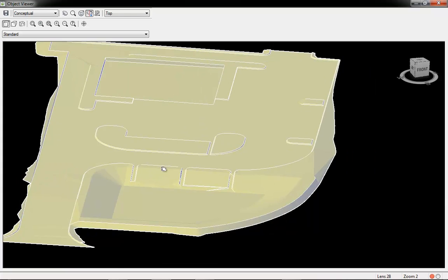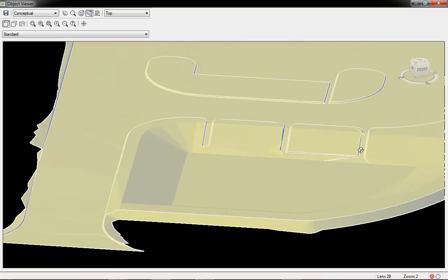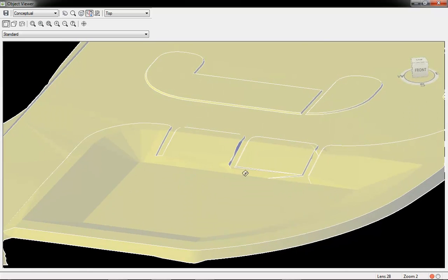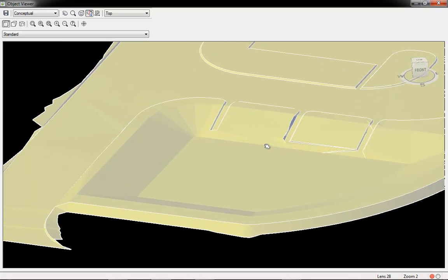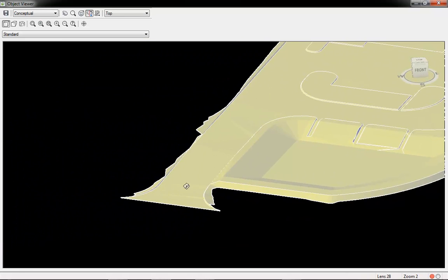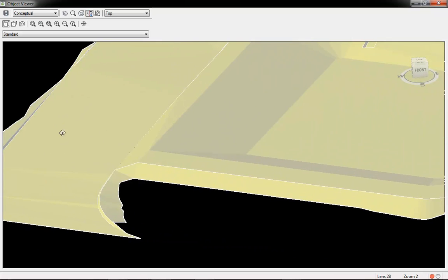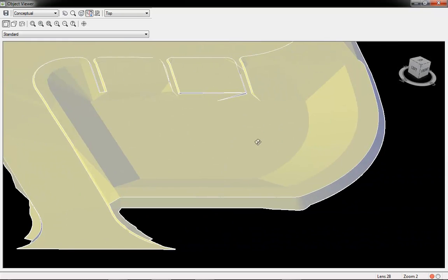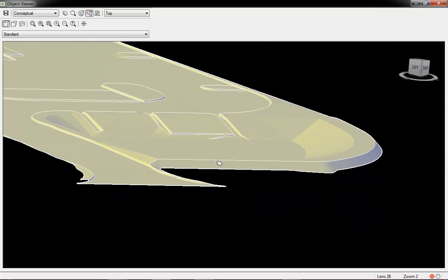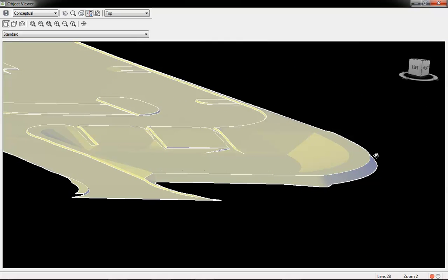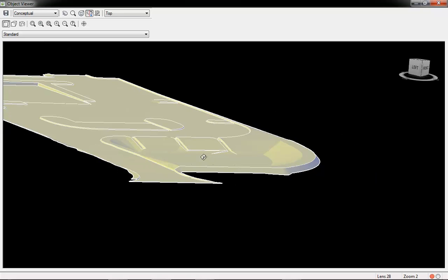So for water that's flowing downhill this way, it'll have a chance to escape and come on around and fall into the pond. So we had these open curb openings here for water to drain in. And then obviously you can see the pond that has been modeled as well. And also here next to the pond we got the driveway connecting to the existing road. And on this southern edge of the pond, you can see that this is a quite steep area, and this is actually the retaining wall that is illustrated on your drawings by the 3 contour lines out front. So there you go.